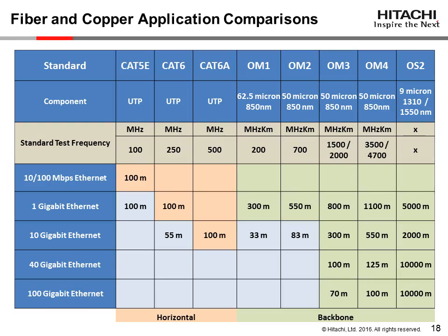This slide shows several current Ethernet applications and corresponding installation distances of copper category cables and the associated fiber optic cables for the same application. Notice in this chart that category cables lend themselves to high connectivity uses in the horizontal plenum environment, highlighted in orange, and fiber optic cables lend themselves to longer distance backbone applications, highlighted in green, found in building-to-building, outdoor, and vertical riser uses. The next two slides graphically demonstrate distance and bandwidth comparison of Category 6A and an OM3 fiber for 10 gigabits per second Ethernet application.